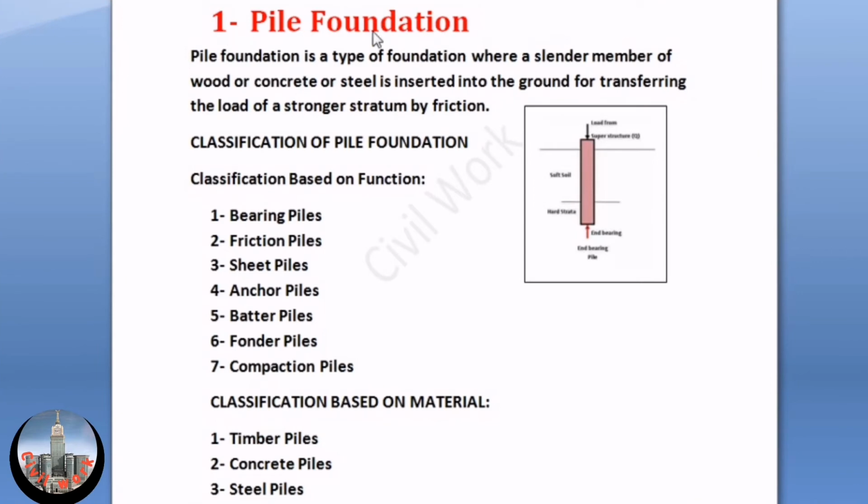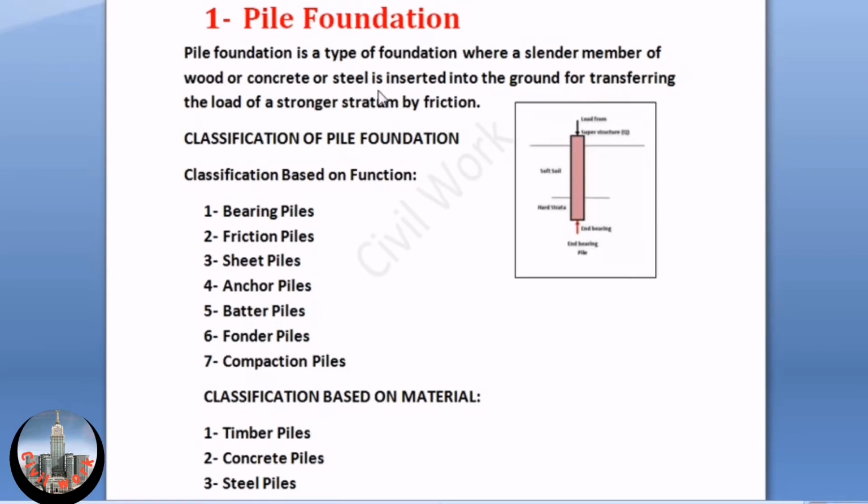Number 1. Pile foundation. Pile foundation is a type of foundation where cylindrical members of wood, concrete or steel are inserted into the ground for transferring the load to a stronger stratum by friction.